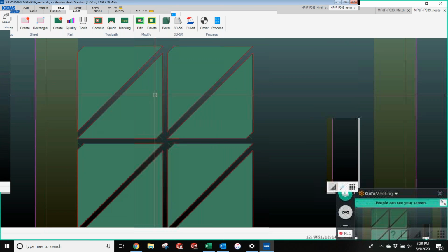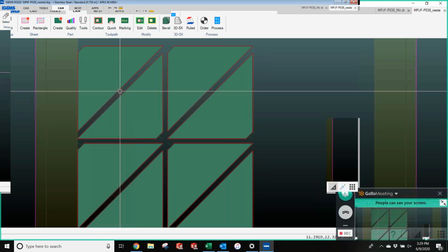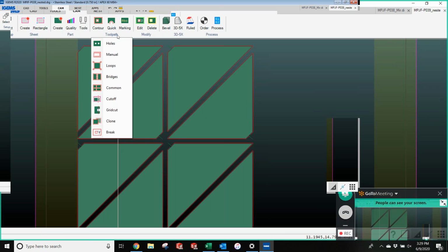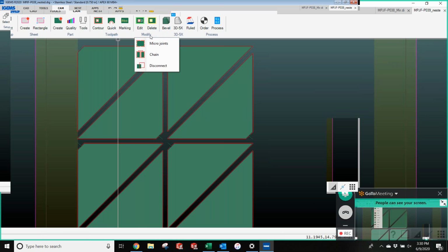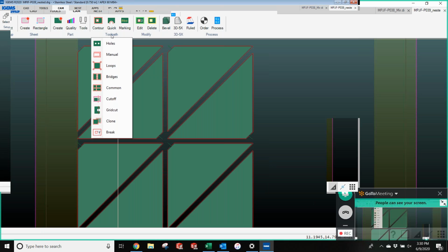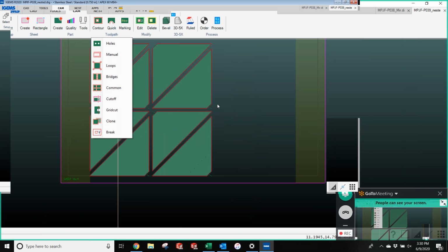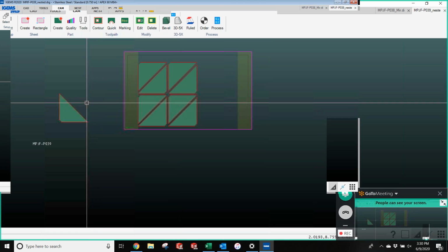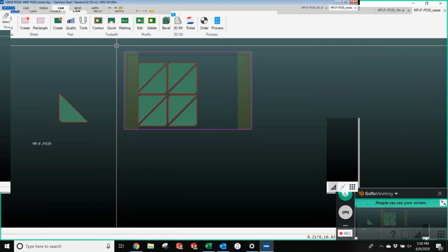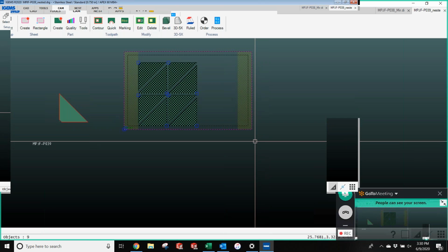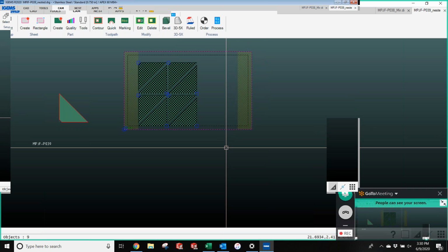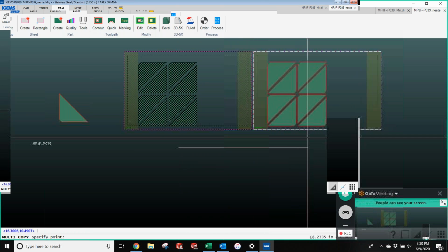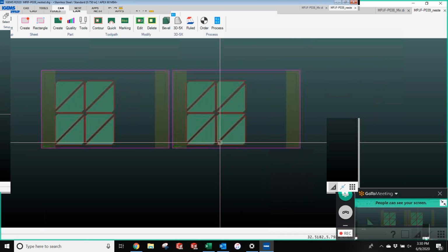And it might not apply to a part like this where you don't want to have any dings on this edge, but there is also, you can do things like chain cuts or, what do they call it on the other one here under toolpath? There's bridge cuts, where basically with one pierce you could do a bunch of parts and have them all chained together. So let me just show you how that would work. Again, on this part where you want the lead in a particular point it might not work, but there might be situations where this can be helpful. So let me just copy this over to here so you can see how this would work.